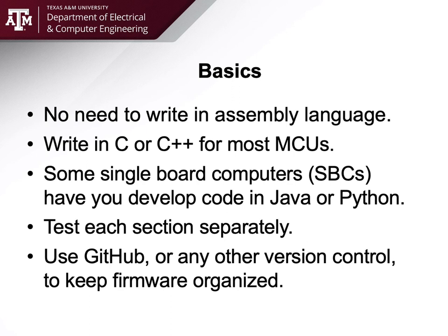Really simple. You don't write all your code at once, stick it all in main, and hope it works. Write all your code as independent little blocks. Test each one individually. That way you can rely that, hey, the A to D converter code I got working, I don't doubt it works. So if you're getting some weird result in your algorithms in your main function, you can probably rest assured it's not that function.